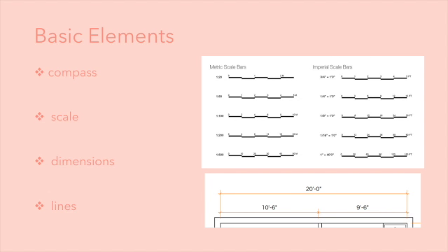Doors, furnishings, cabinets, and interior walls will be drawn a little bit thinner than your exterior walls, and then any action lines or information lines and patterns, like hardwood flooring, will be drawn with super light, thin lines, because they're not as important.